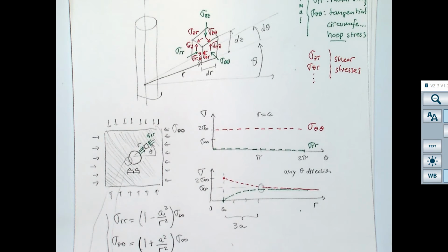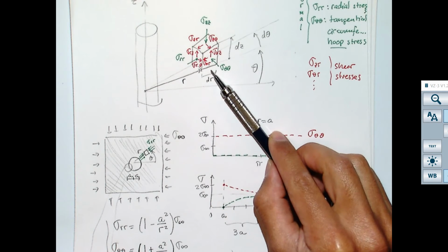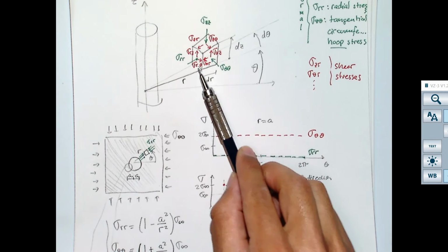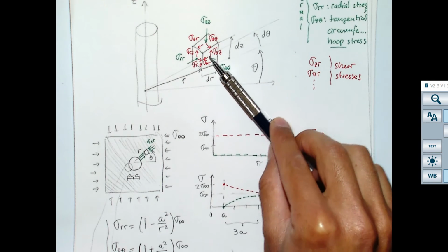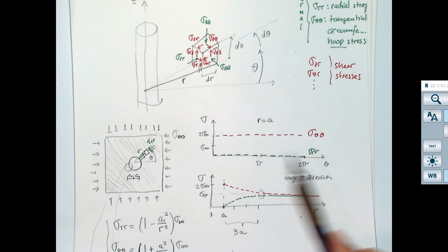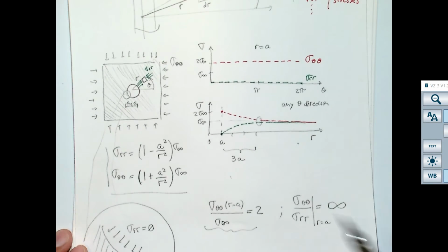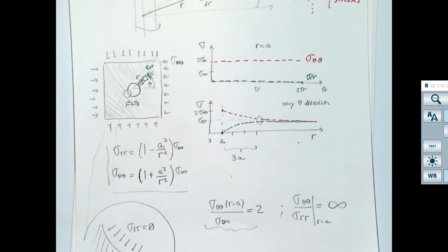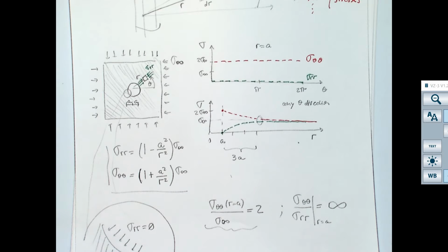the first step was to understand cylindrical coordinates. And the most important thing to remember here is what is radial stress and what is hoop stress. The radial stress is a stress which is in direction of the radius, and the hoop stress is the one perpendicular to that one on the plane perpendicular to the axis of the wellbore. So now if we look at the wellbore from the top, we are going to be able to see what are going to be the stresses around this wellbore when we add different types of loadings.